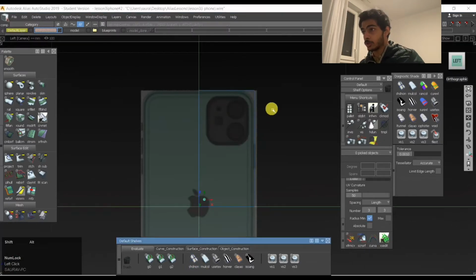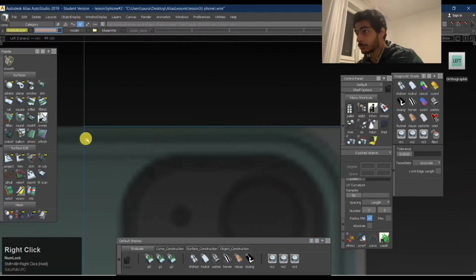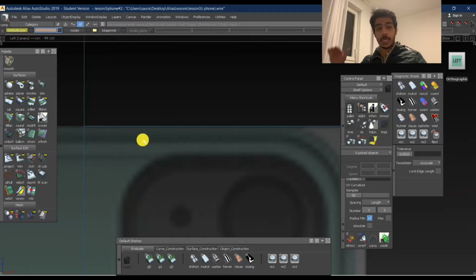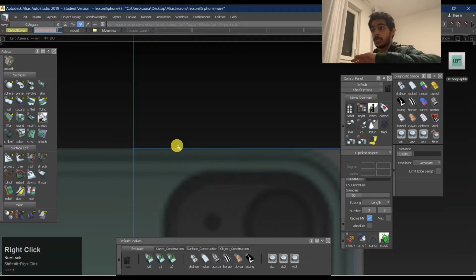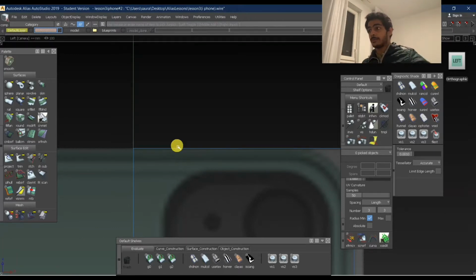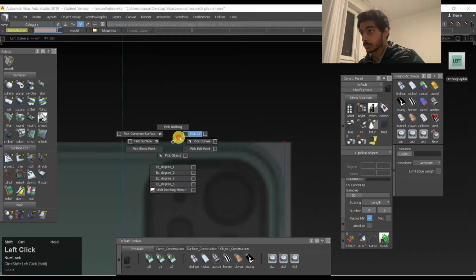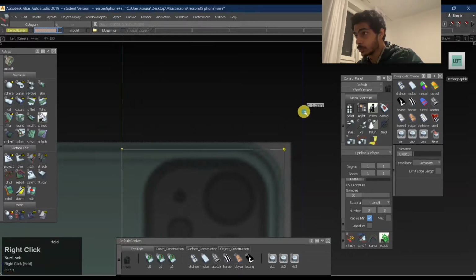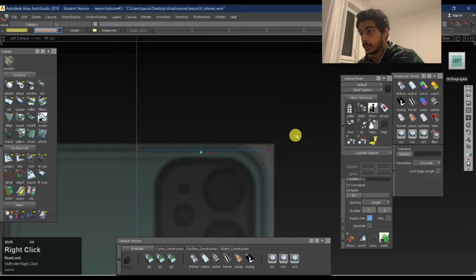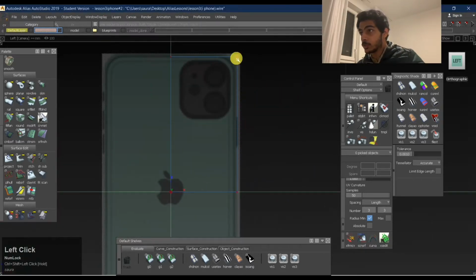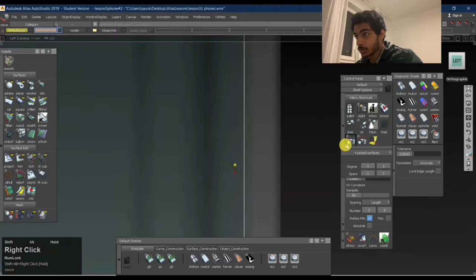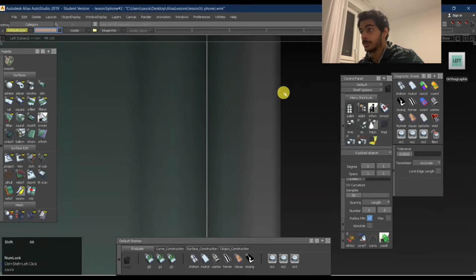We'll come into the orthographic view, and now if we see, there's a dark line over here. We need to bring these surfaces down so that the crown can start from the black line over here, right? That's the point from where the surface is actually starting to have a crown. So we'll again pick the surfaces, Control on, pick the CVs, we'll bring them down over here. On this side, we'll pick the CVs over here and bring them over here on this side.